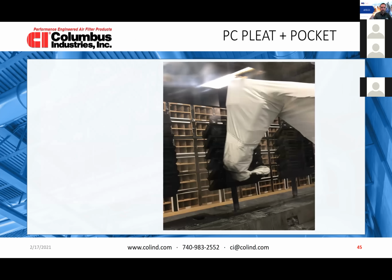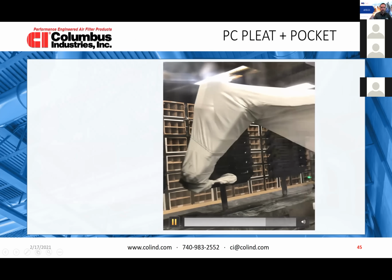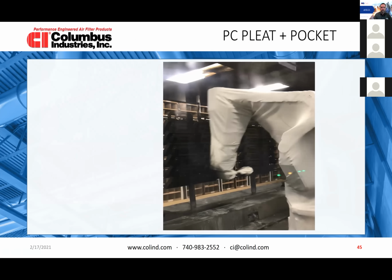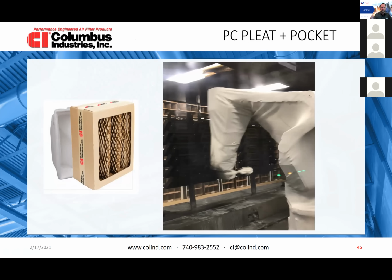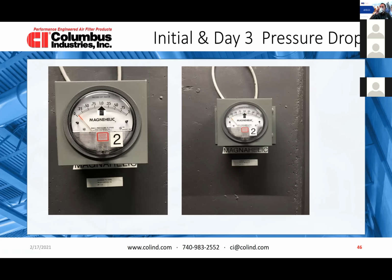This is the application. It's a robot application, very heavy paint, a lot of parts going through. And we went in with the combination of the PC Pleat and the pocket. Remember, they were changing filters every 6 hours, the back filters every 3 days, and the other ones every 24 hours.